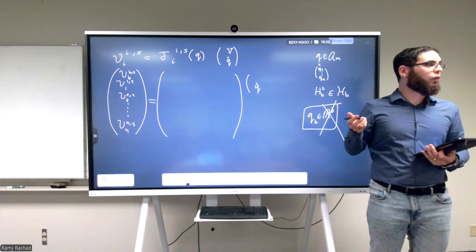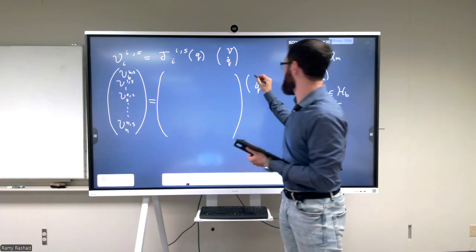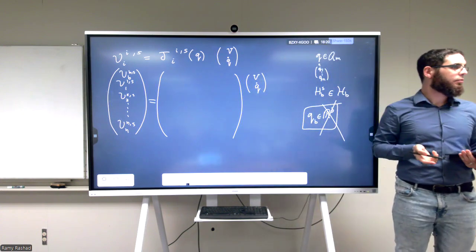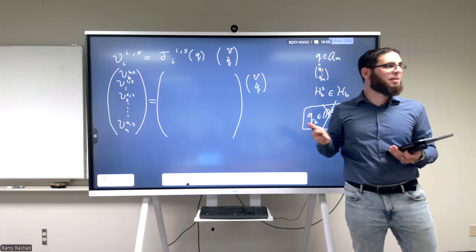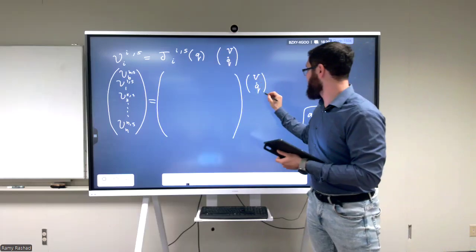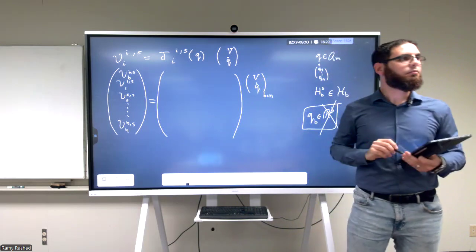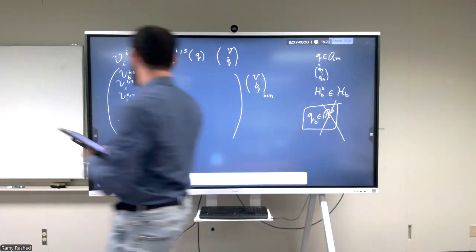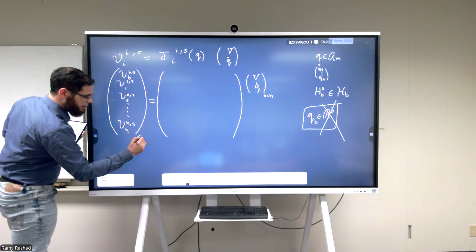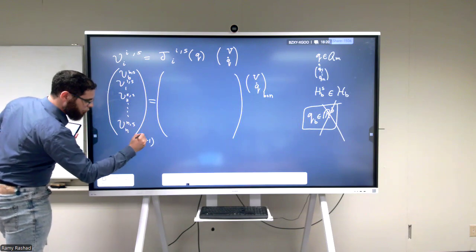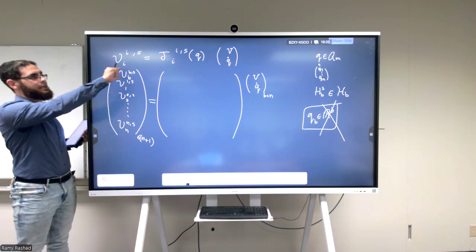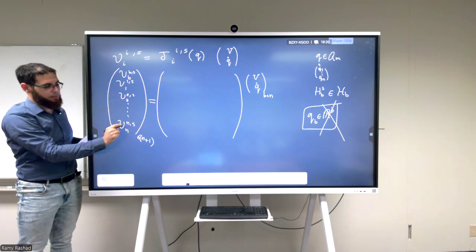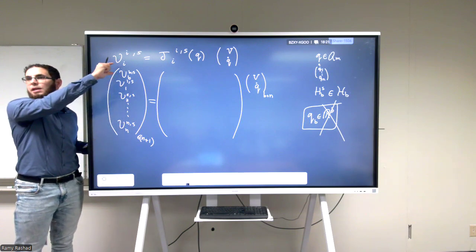But here the base is also moving. And the base has a velocity that's given by this small v that has a dimension of b. So this is a b plus n vector. You agree? So b dimensions, n dimensions. This is a 6n plus 1 vector, because this is 6, 6, 6, 6, 6, and so on. So I have 6 of these multiplied by n, and I have 1 extra 6, which is the base.